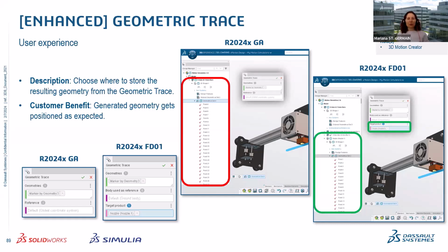There was a quick question from Andre about SolidWorks, if it supports Altium Designer. Vance, if you could also answer it live for the benefit of the audience. Certainly. So yes, SolidWorks is CAD agnostic. What I mean by that is it will work with any PCB design software. Today I was presenting that it supports the newest standard, which is IDX, which supports the most data types. Altium uses a slightly older standard called IDF. We support that and everything back to the earliest of the standards.